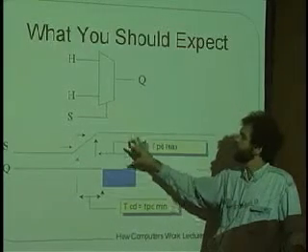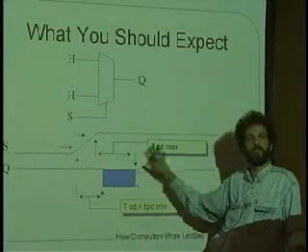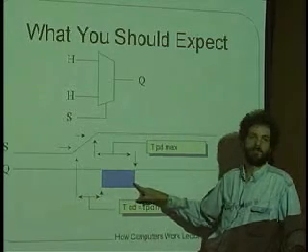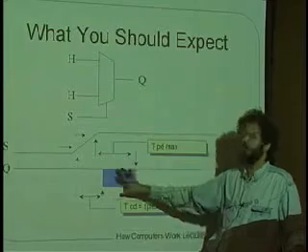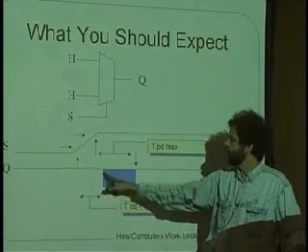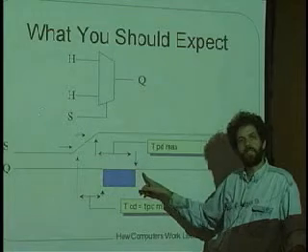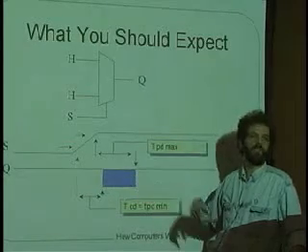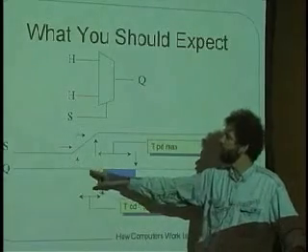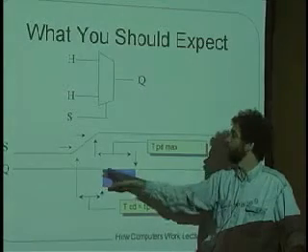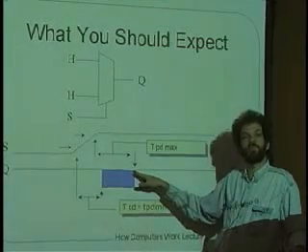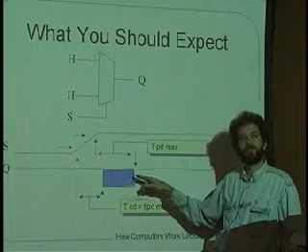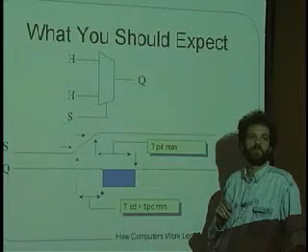Okay, if we were given the specifications for the device in terms of TCD and TPD, what that would say is if a hazard is going to take place, it'll happen somewhere during this blue time here. Okay, and so that's what the meaning of the difference between when the TCD is up and when the TPD is up. That during this time on the output, kind of all bets are off. We don't know what the output is going to be because we only guarantee that we'll hold on to the old value of Q up to here, and we only guarantee that we'll start putting out the new value of Q over here. And in between those two times, in general, in logic circuits, we don't guarantee anything at all. Okay?